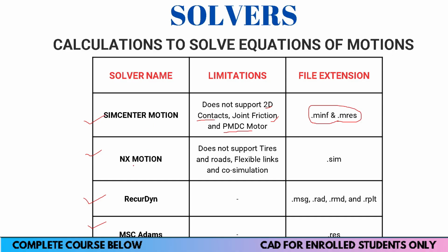Coming to NX motion solver, the file extension that it uses is .sim. We are going to deal with this, but it also has a drawback that some certain industries that use tires and rods, we won't be able to use, and some flexible links also we cannot use when you are using this type of solver. And co-simulation, that means when you are importing control system from some other softwares like MATLAB, you cannot do that.